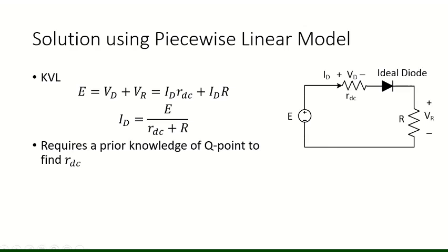So it's Id RDC plus the drop across the resistor R, which is VR, equal to Id into R. As we knew that the same current will flow from this diode and the resistor R, so both currents are represented by Id, which are called the diode currents.